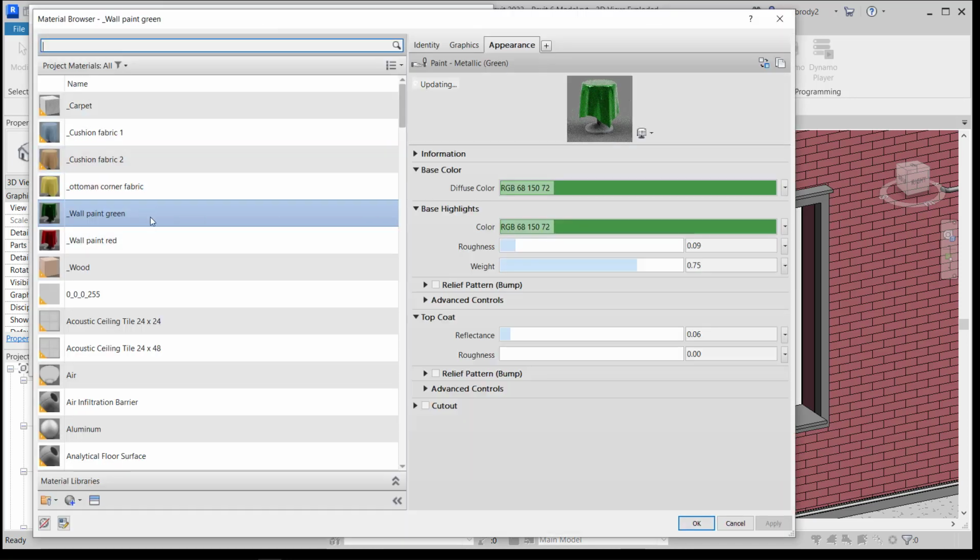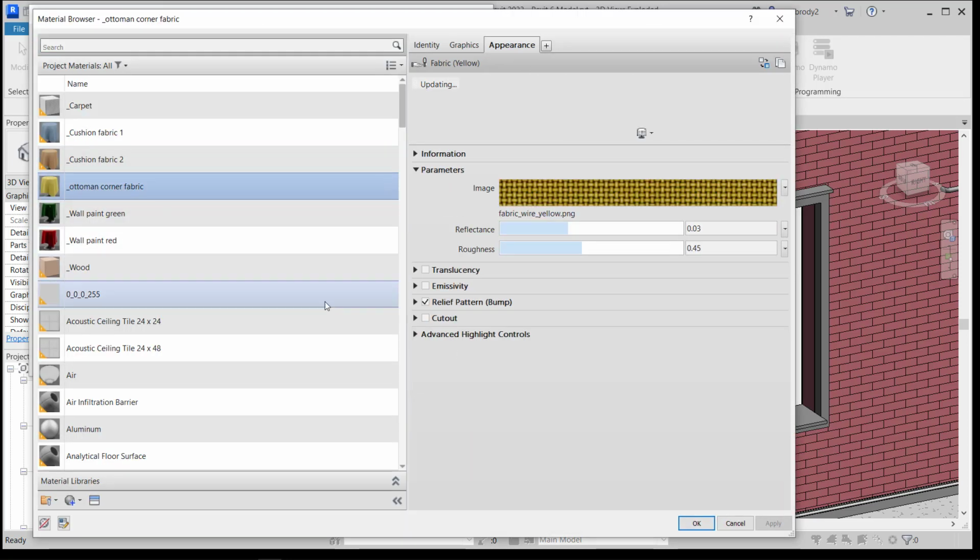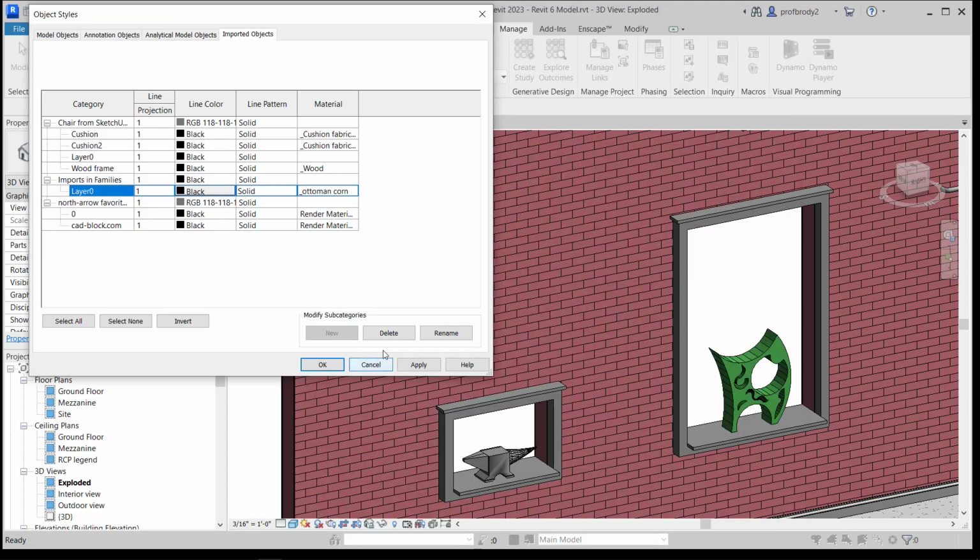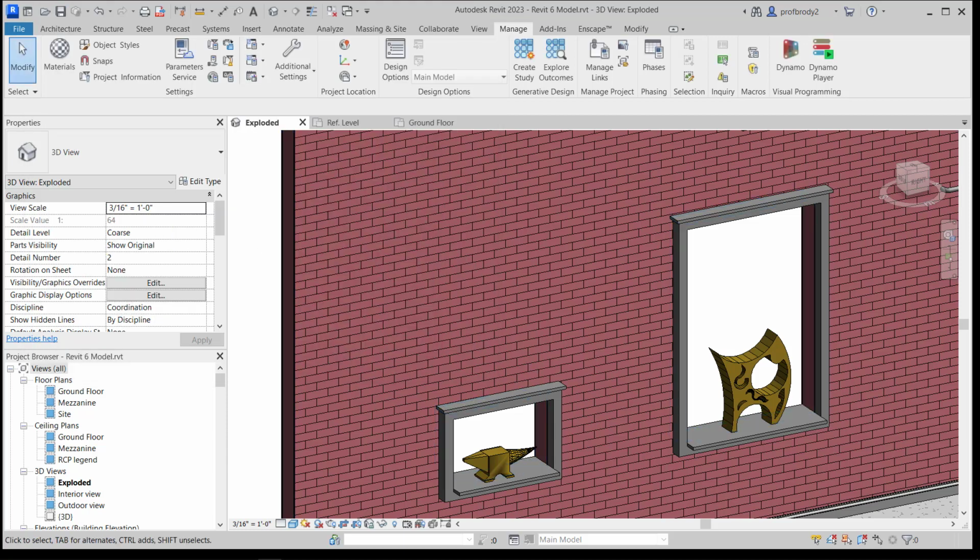If I just go in here and I pick here, I'll make them out of fabric because that makes a lot of sense, and hit apply, you should see the objects change color appropriately. That's basically all there is to it. Create 3 different family types, which are distinct. Hopefully they flex properly and you can get the different dimensions to work, and insert them somewhere into your project.